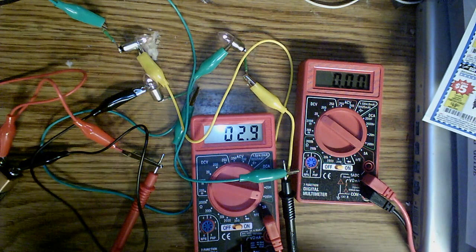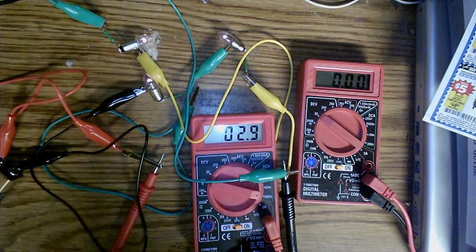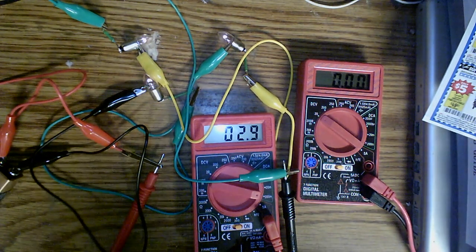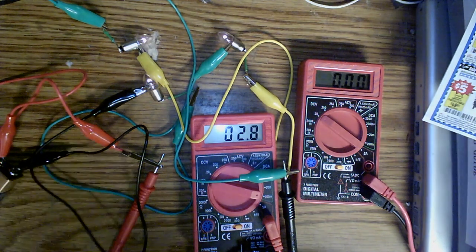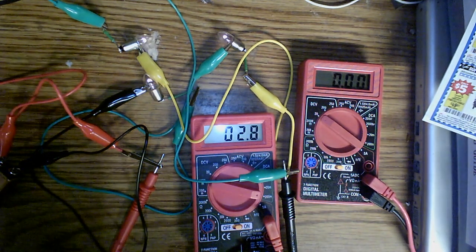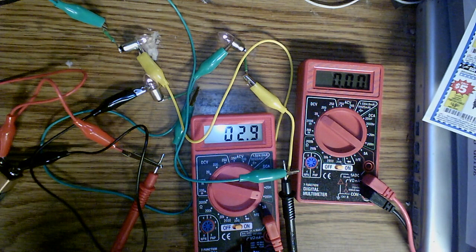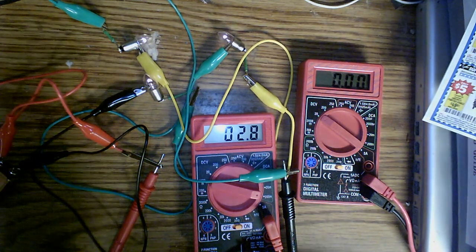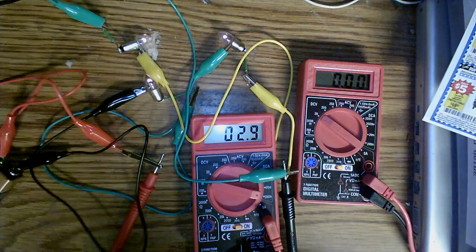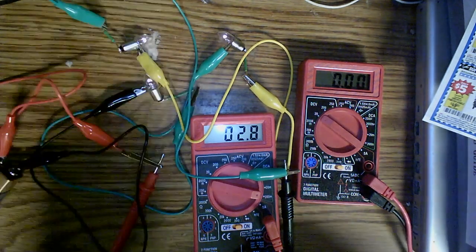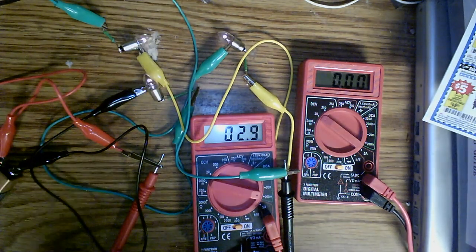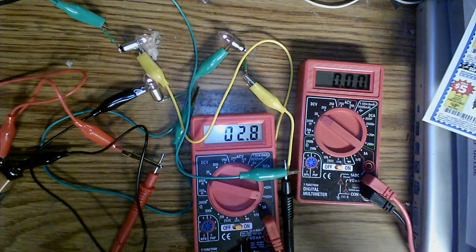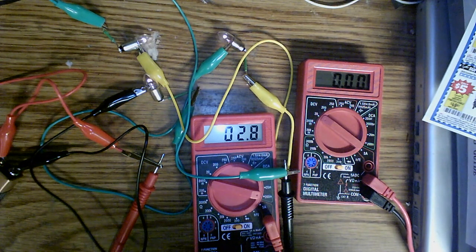So what we're seeing is that, assuming all these resistances are exactly equal, the voltage drop should be exactly equal as well. Now we're not seeing exact numbers. Why? Well, different lengths of wire were used in each of the little pieces that are sticking off the bottoms. Some of the soldering might not be as good, and so we may have more internal resistance built up. But that's basically it.